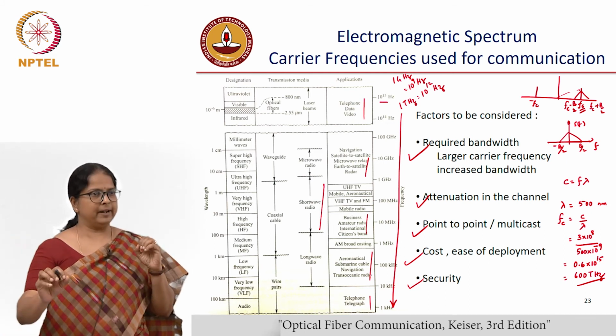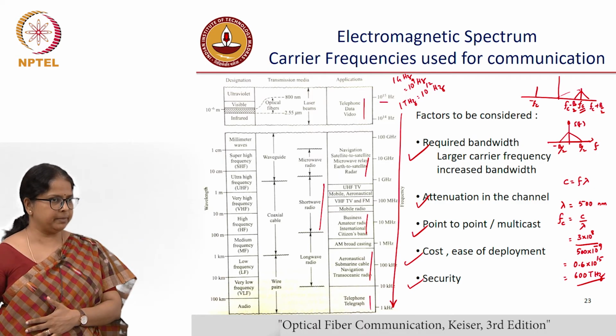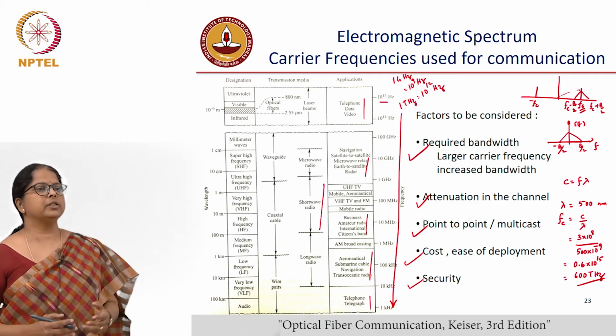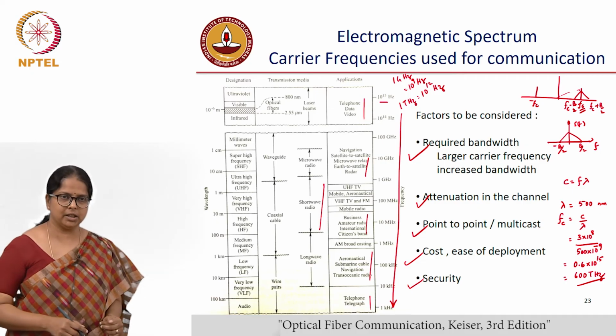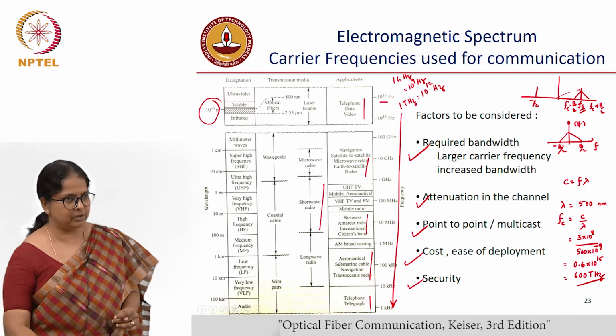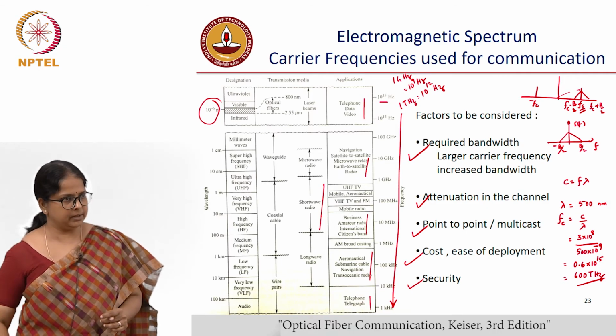But in an optical fiber, green has a very large attenuation. So we will talk about attenuation in optical fiber separately, but green or blue green is a color which is used for free space communication in underwater communication scenarios. So that's the left side, wavelength on this side and carrier frequency on the other side.